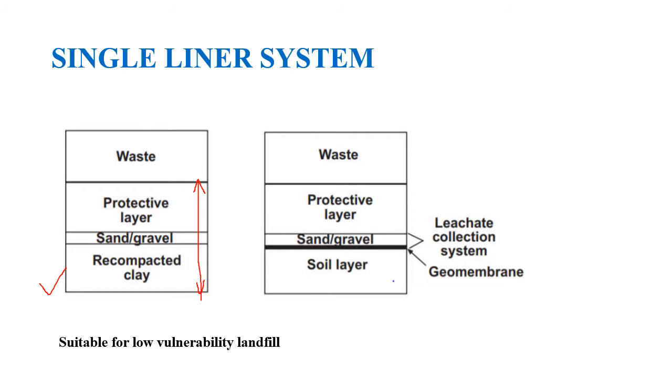the drainage layer. Now, for the drainage layer, as a natural material, we would prefer gravel because it will serve the purpose. So gravel will serve the function of drainage. In order to collect the leachate, all these leachate collection pipes will be embedded within this layer, and once the filtered leachate passes through the drainage layer, it will be collected into the respective leachate collection pipes embedded within this layer. And then it will be taken out of the landfill to a treatment facility.